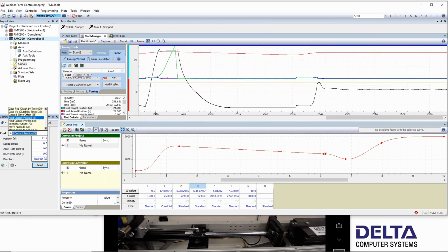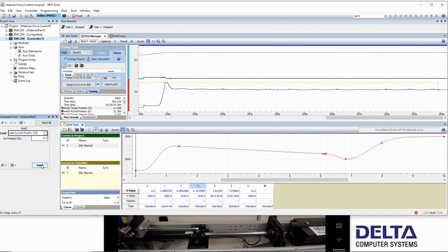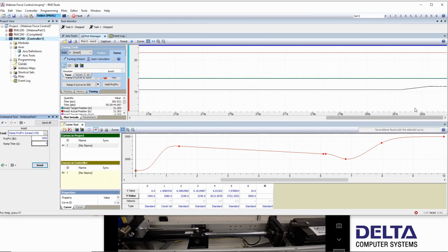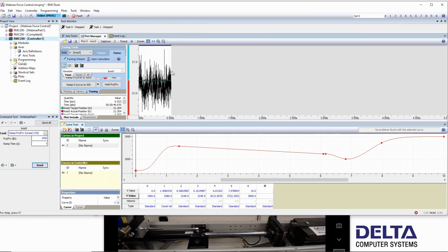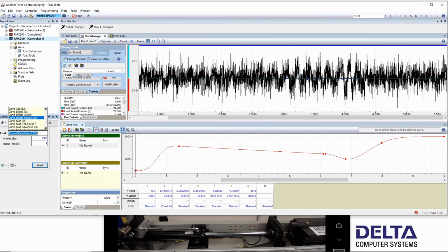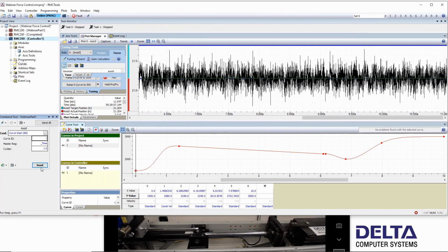So I can now do the hold current pressure force command 19 over here in the command tool, click send, and notice in the plot now that force that was waving around is nice and solid, so it's obviously controlling it. And I need to ramp to the beginning value of the plot, which is 1500. So we'll ramp to 1500 over a second. Looks like it's there. I'll stop this, trying to start a new one so it changes the zoom a little bit. And now I'll do the curve start command, and that was the curve ID 1. And we'll click send.